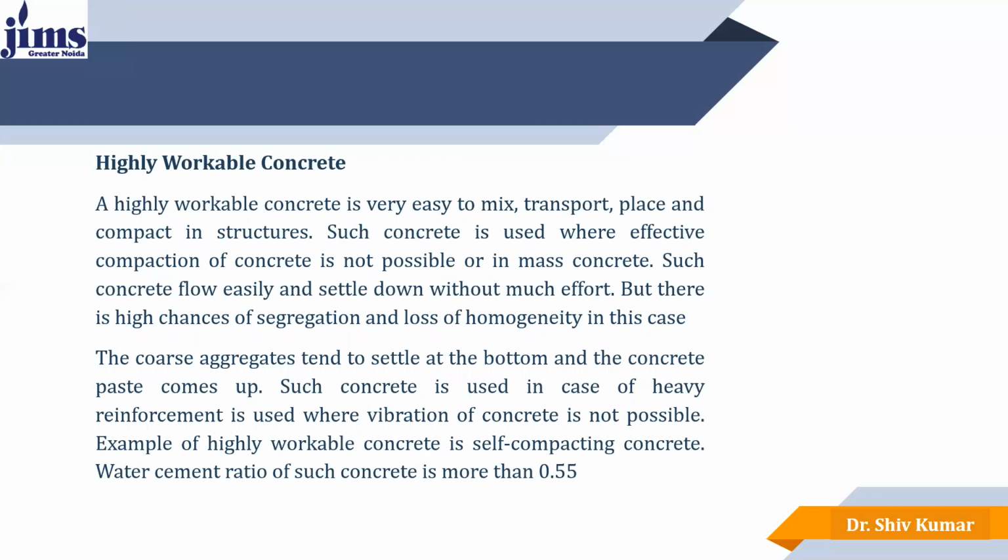Now, the next is high workable concrete. It means the water cement ratio is high, above 0.55. It is highly workable because it can be easily mixed, transported, placed, and compacted in the structures. Such concrete is used where effective compaction is not possible, or in mass concrete. It flows easily and settles without much effort. But here there are high chances of segregation and loss of homogeneity.